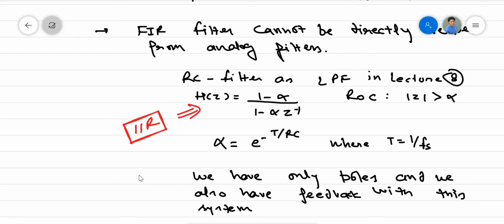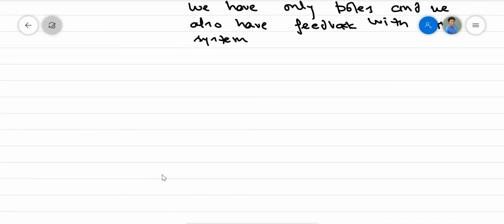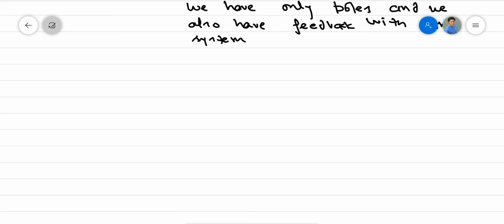Now another important point for a FIR filter, which we discussed in the last lecture, is about symmetric and anti-symmetric filters. With that property, type 1 filters, which can have response for high frequency as well as low frequency, are the most versatile filters.